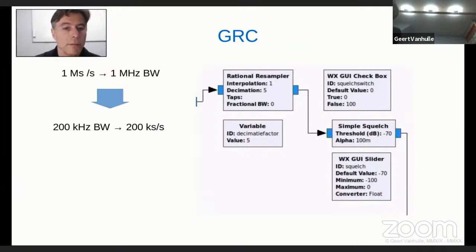So instead of cutting off the audio, what we'll do here is a digital calculation of the signal-to-noise ratio. And if this calculated digital signal-to-noise ratio drops below a certain level, what I will do is not stop the sample stream, because that would give problems in my flow graph. I will replace the value of the incoming samples with 0 samples.